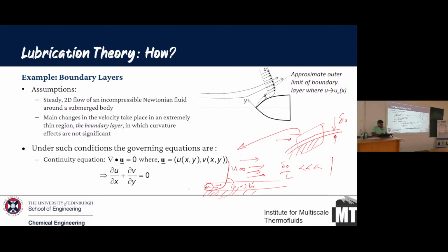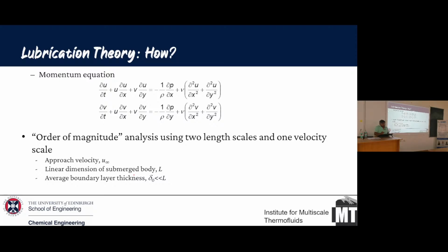Okay, so if you look at this, we have a simple continuity equation, del u by del x plus del v by del y. Now, because it's a 2D system, we can have a 2D momentum equation as well. Okay, so this is your boundary layer. This is my y-axis. This is my x-axis. And u and v are in action over here. This is how your velocity profile looks. Because it's such a thin thing, we are not even considering gravity, the effective gravity is almost 0, because it's such a thin film. So we don't have a rho g term here.